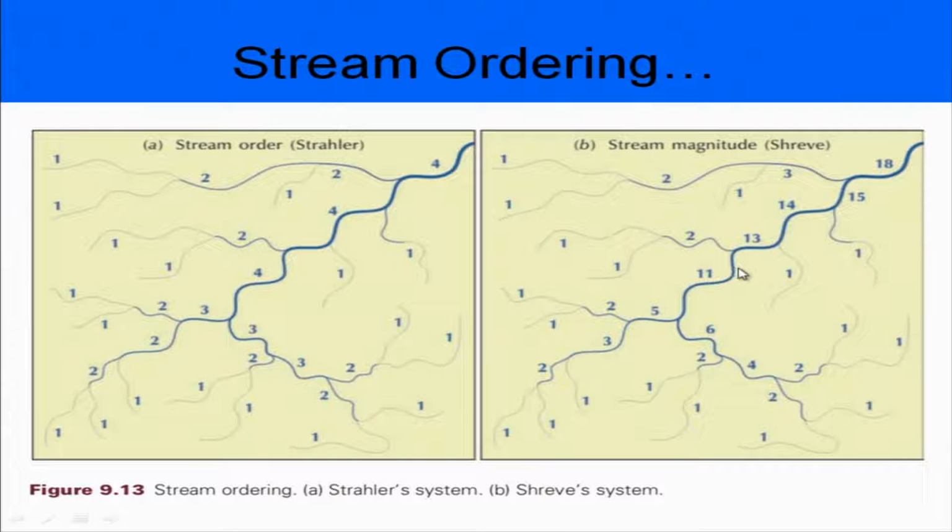So this is not commonly followed, and the Strahler classification is mostly adopted. Here, two first order streams become second order, and then this becomes the fifth order and much higher, because you have a fourth order here and all that. So the classification is very random here, and that is one of the reasons why this has not actually been used.